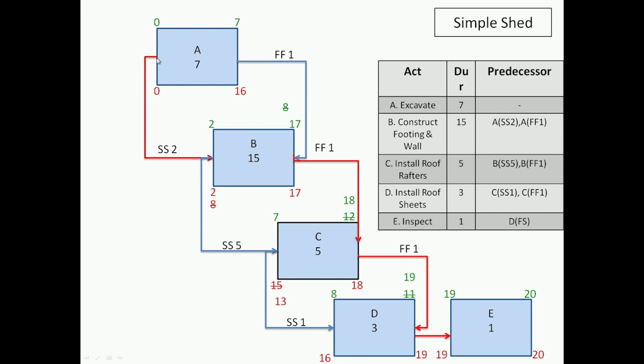So for example, if I say I am going to start excavating and then end of excavation is not critical, it does not mean that I can start excavation and stop, because I have to keep excavation ahead of constructing the footing. If I do not keep excavation ahead of constructing the footing, somewhere B is going to stop. So here you can see B is fully critical, but A is only the start is critical, but it does not mean that I start and then I stop A because I have got things started.